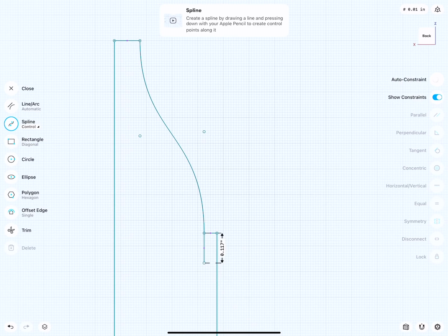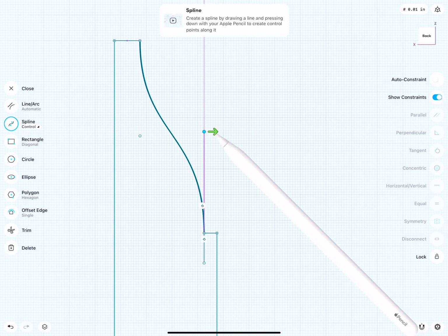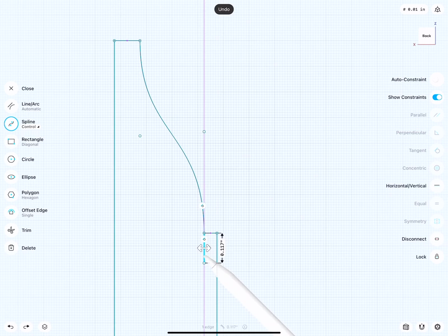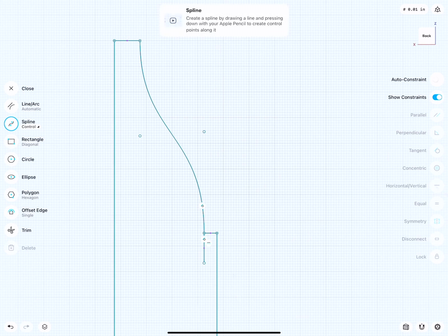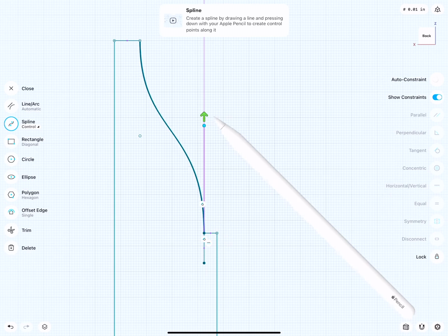Let's give this a proof. There and there. Tangent. You see, the point didn't move. The idea of tangency is that I cannot really move this point left and right. Of course, in this case it did. This line was actually not set to be horizontally constrained, and I lock it. So here, I cannot move it left and right. Only goes up or down.